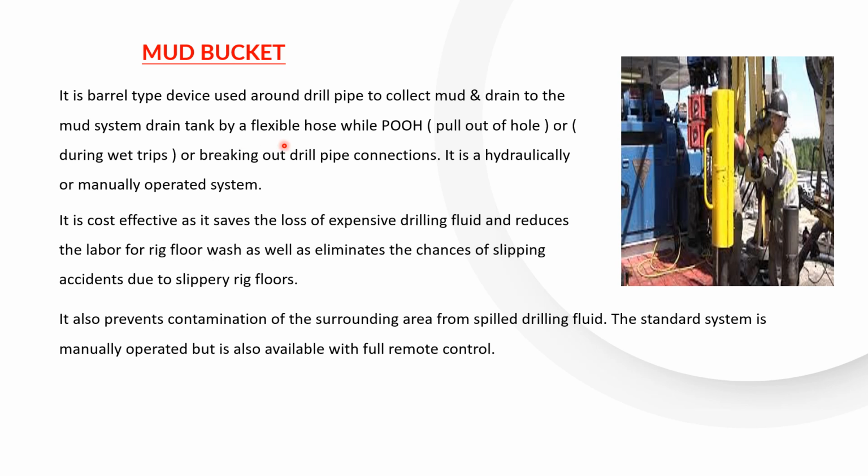Because the mud is expensive, and even the chemicals involved are dangerous, there are many reasons we cannot spill the chemical mud anywhere. If on the rig floor, it can lead to a slippery or contaminated atmosphere. It can be hazardous due to inhalation, due to the contaminated atmosphere.